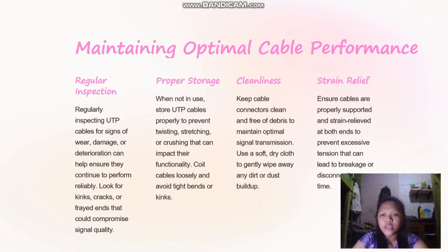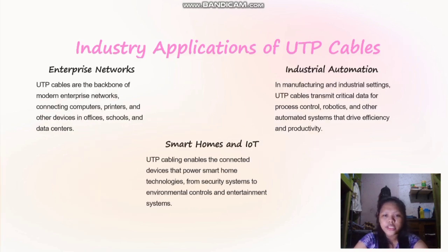Strain relief. Ensure cables are properly supported and strain relieved at both ends to prevent excessive tension that can lead to breakage or disconnection over time.